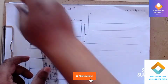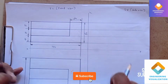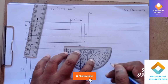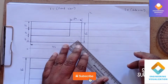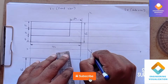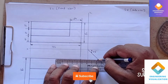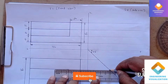In order to connect the side view with the top view, we should construct the 45-degree angle line. This concept you all know. To connect the top view with respect to the side view, we should construct the 45-degree angle line at the intersection of X5 and X1 Y1. I'll be placing the protractor and marking the 45 degree angle. Now draw a straight line passing through this 45 degree mark. So this has an angle of 45 degree. Now project the lines from the top view until they touch the 45 degree angle line.